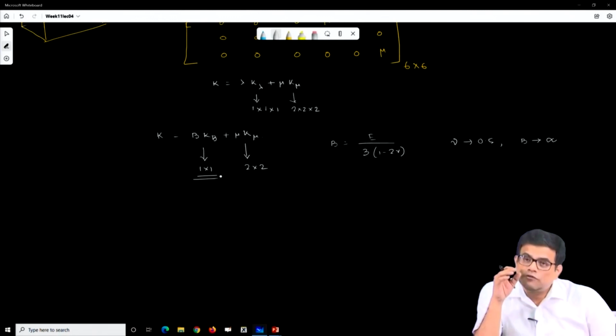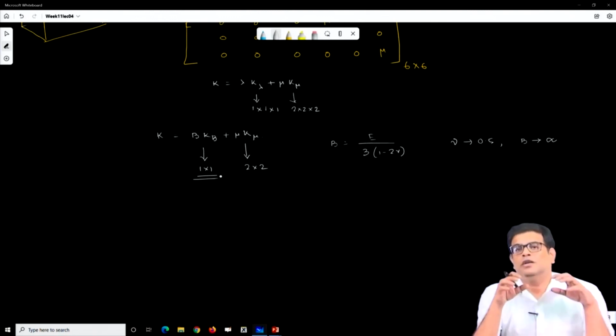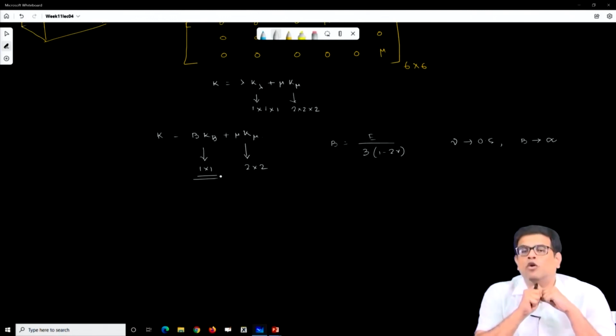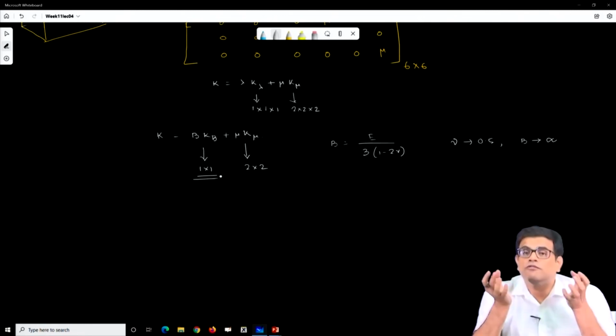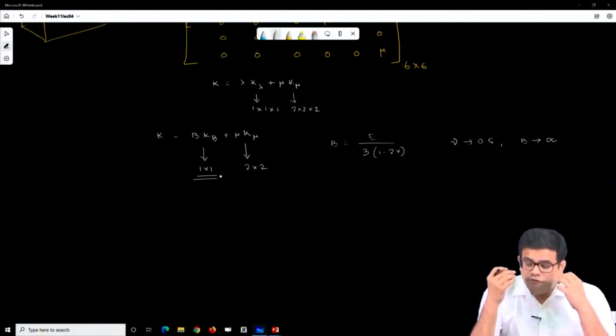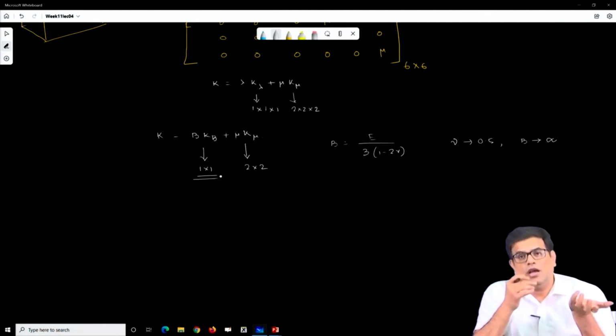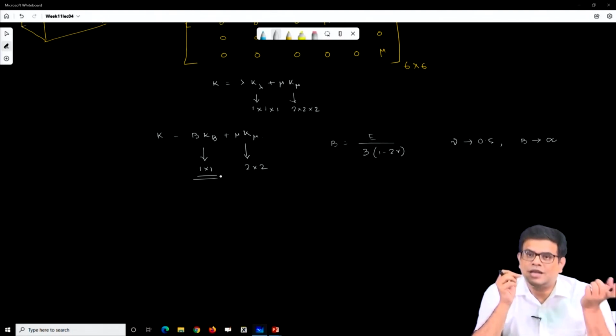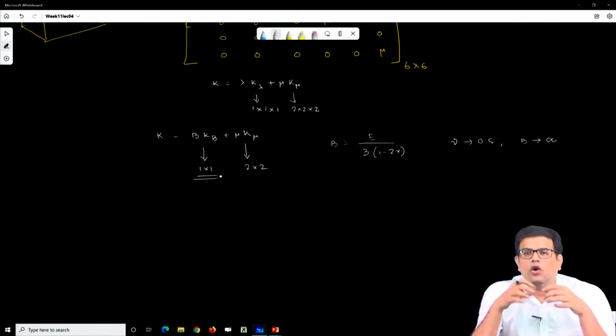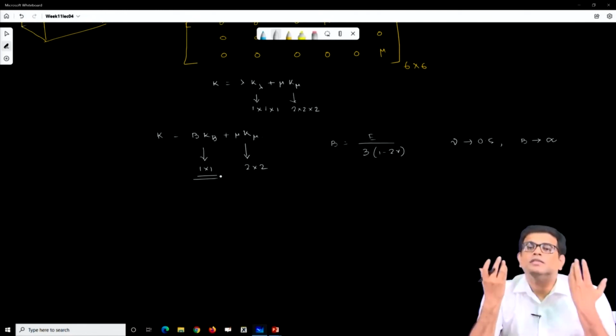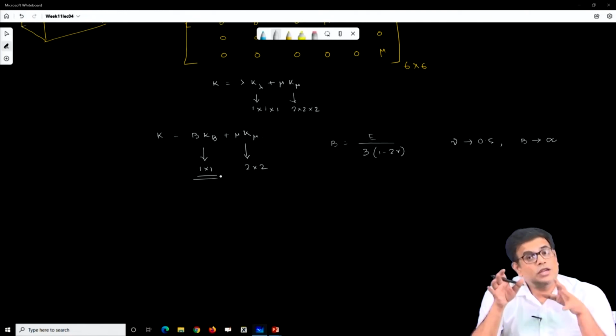So in case of volumetric deformation, when it is 0 in a body, with the full integration rule we experience volumetric locking in the finite element solution. Likewise, in case of a thin structure, like we have seen with a thin beam, we experience shear locking. So when Poisson's ratio goes to 0.5, we experience volumetric locking, and this is for linear material.